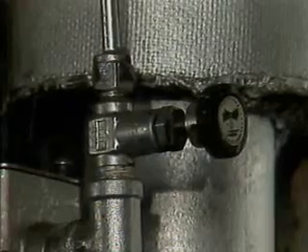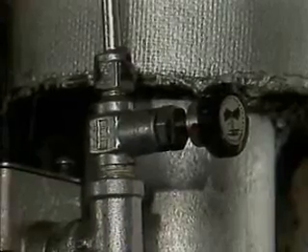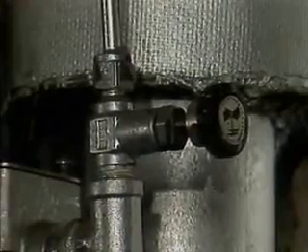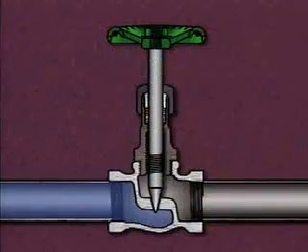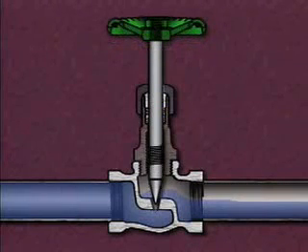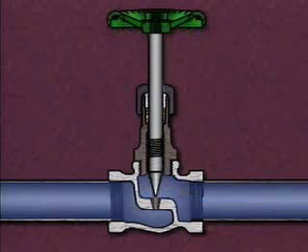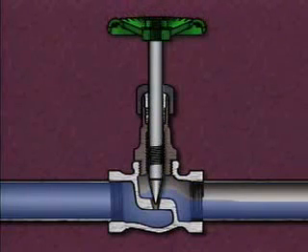Needle valves are generally smaller and longer in relation to their piping than other types of globe valves. As this cutaway illustration shows, a needle valve's seat opening has a very narrow diameter. When the valve closes, the disc descends deep into the seating area. A small movement of the valve stem causes a small, gradual change in the flow rate through the valve, which makes the valve capable of precision throttling. So needle valves are often used when precise regulation of flow is needed.